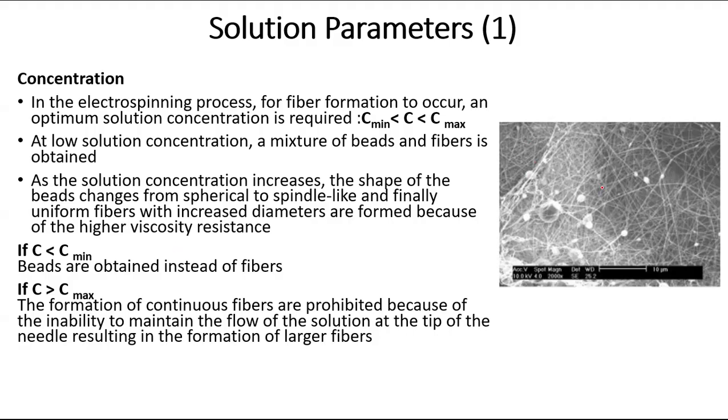So if the concentration of your liquid polymer solution is lower than the minimal concentration, beads may start occurring. If the concentration is greater than the maximum concentration, the formation of continuous fiber cannot be done because it cannot maintain the flow of the solution. Therefore, you should be expecting large fiber formation.